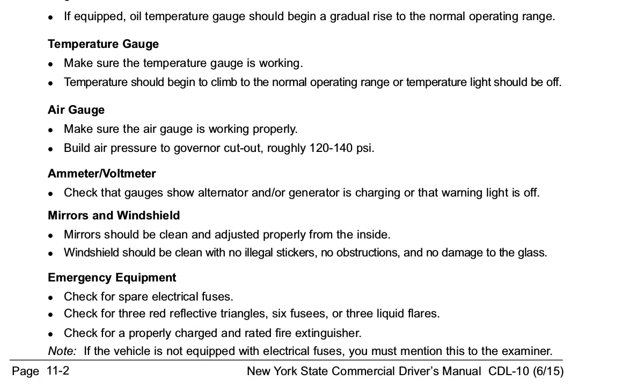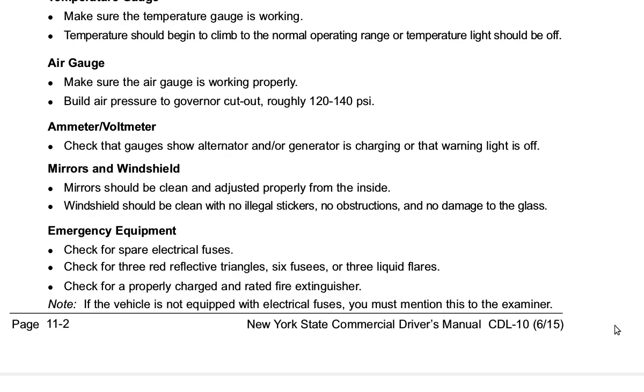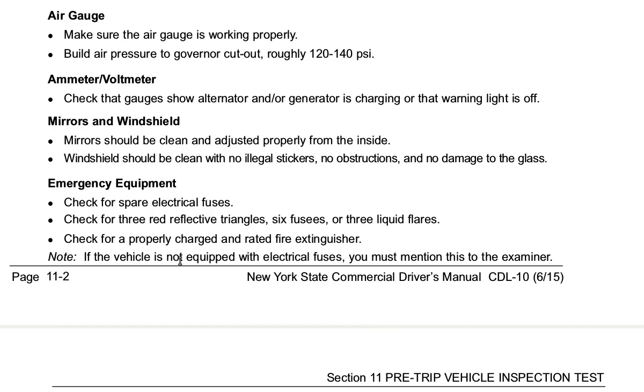Mirrors and windshield. Mirrors should be clean and adjusted properly from the inside. Windshield should be clean with no illegal stickers, no obstructions, and no damage to the glass. Emergency equipment. Check for spare electrical fuses. Check for 3 red reflective triangles, 6 fuses, or 3 fusees, or 3 liquid flares. Check for a properly charged and rated fire extinguisher. Note, if the vehicle is not equipped with electrical fuses, you must mention this to the examiner.